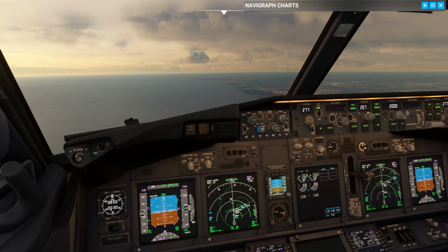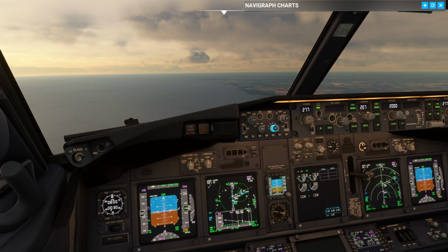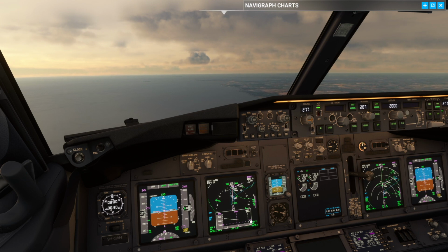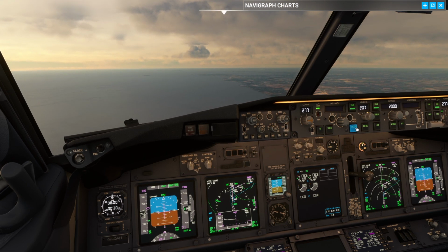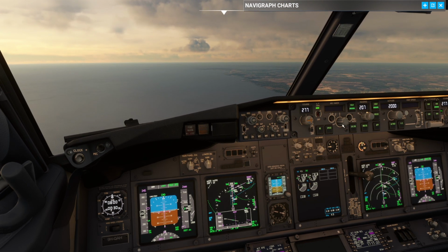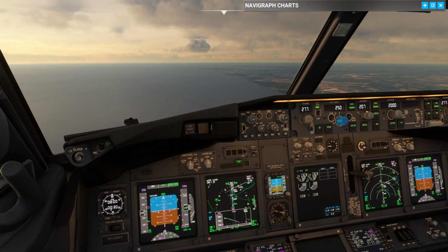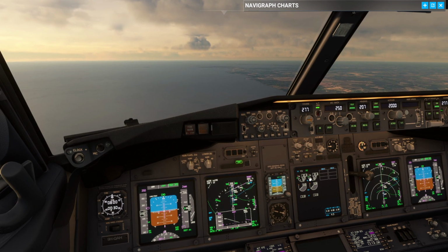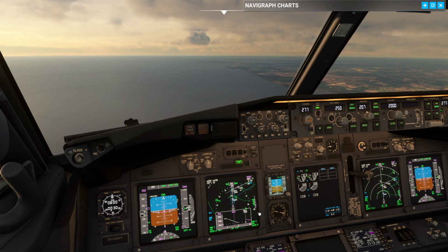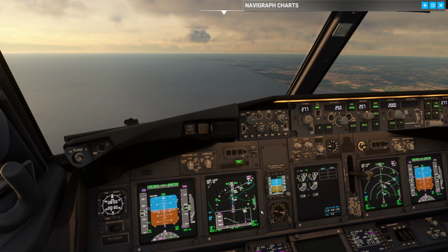Now, the pilot monitoring should have the VSD open at all times so that the pilot flying can reference the path and also call if the terrain is in sight when we are going to come closer to the runway. So now we are back in VNAV speed here because we're a little bit above the path. I'm just going to help the aircraft get back on path here. Coming in nice and slowly, and we should catch VNAV path any minute there. There you go.